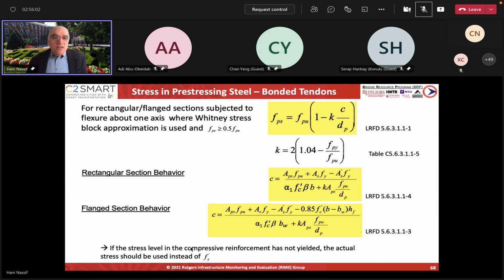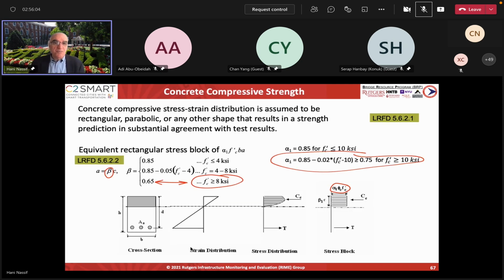So now, for reinforced concrete, versus pre-stressed, reinforced concrete is very simple because you usually have the area of reinforcement, okay? And you have two equations, two unknowns. You have C and T, that's one equation. The two forces are equal to each other. Second equation is sum of the moment. Take the moment about, let's say, point T, and you find the moment equation, then you can find the neutral axis, right? And you can find the ultimate capacity of the section.